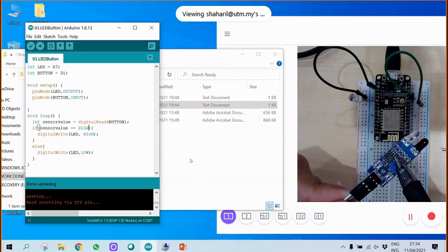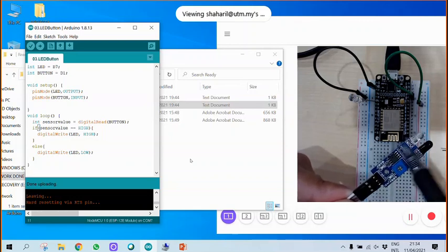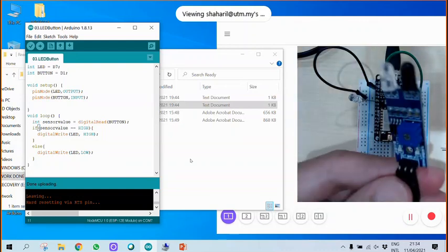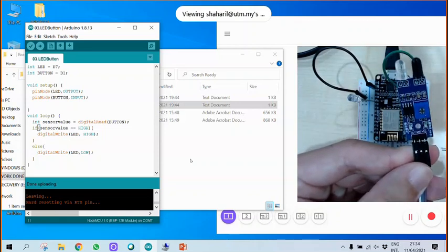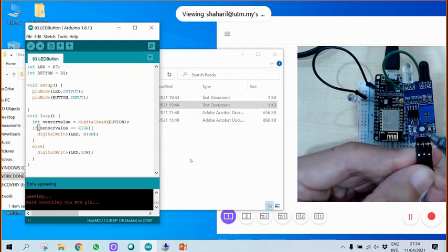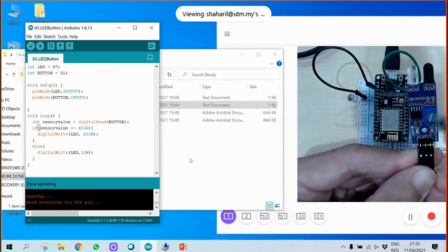When you build the module, it has some ICs, we call it a comparator, and also you have some resistors to set the value for this IC and so on. So this whole part, we call it the module. Okay, so let's see which pins are involved. This is the VCC where you put the supply, in this case 3.3 volt. This center is the ground where you put the ground. This is the output, the data coming through this sensor. So the data is whether 1 or 0, digital data.